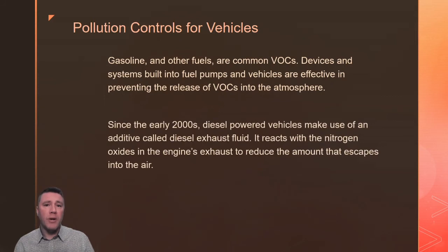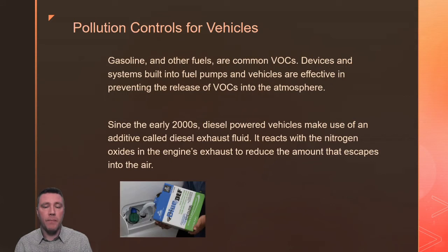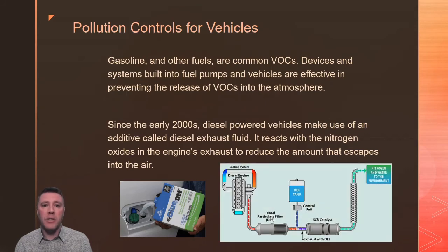For vehicles that run on diesel fuel rather than gasoline, requirements established in the early 2000s mandated the incorporation of a diesel exhaust fluid system. The fluid, added to a tank separate from the fuel tank, reacts with the nitrogen oxides present in the diesel exhaust. The chemical reaction results in nitrogen gas and water being released, two naturally occurring components of air.